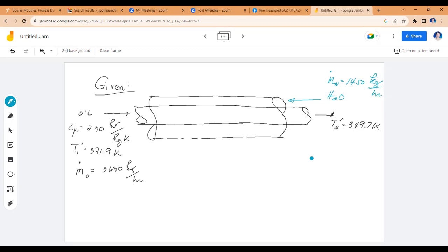Now, the inlet temperature of water, if you recall a representation, so the inlet temperature of water is T sub 2. Since it's the fluid that will have its temperature increased. So T sub 2 is 288.6 Kelvin. Now, I'm just going to place here the arrow where you will have your T sub 1 for your water, your cooling water.